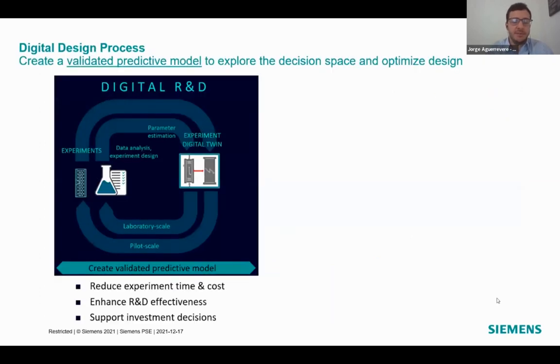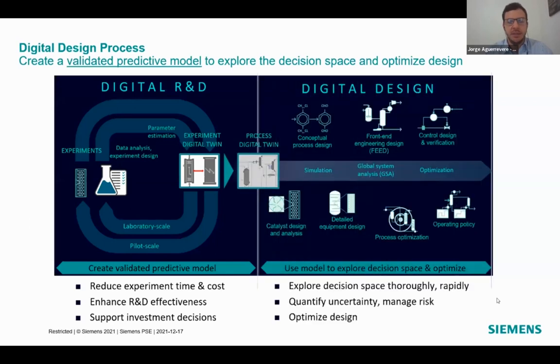And this is a process. It's a very iterative process. You rarely ever get one bit of data, put it into the model, and have a model that's perfectly predictive. So quite often, you'll do this at different scales, put data into the model, compare again with the equipment, maybe scale it up, run the simulations again, compare with new equipment, different equipment, put more data into the model, and you start building up confidence that the model will predict what goes on in the equipment as you deploy it into wider systems. And at this stage is where you have what we call a digital process twin.